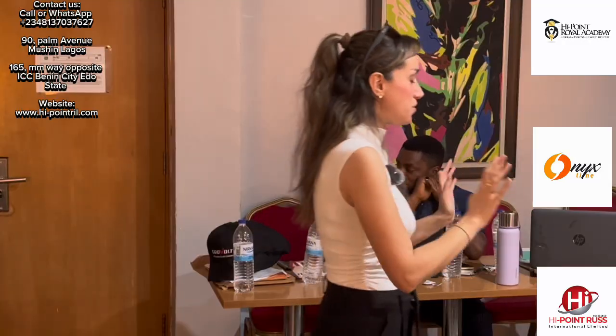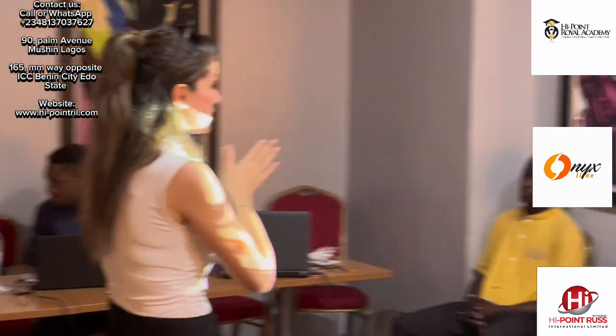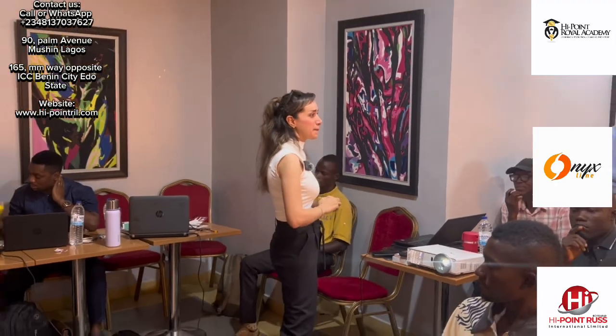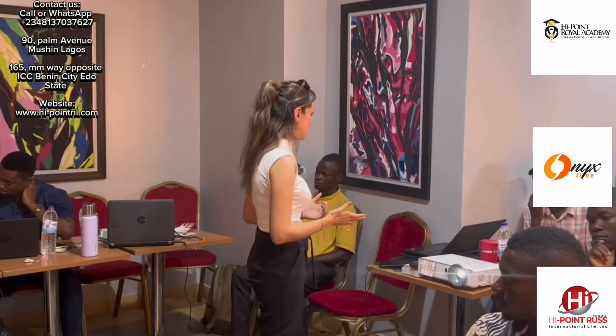Even if in this high voltage battery the R&D told me you can reach 10%, and don't worry, the battery will wake up again. But when I do this project, I put it at 15 because I will be satisfied and relaxed. So you can read what is in the data sheet, but do standard engineering.